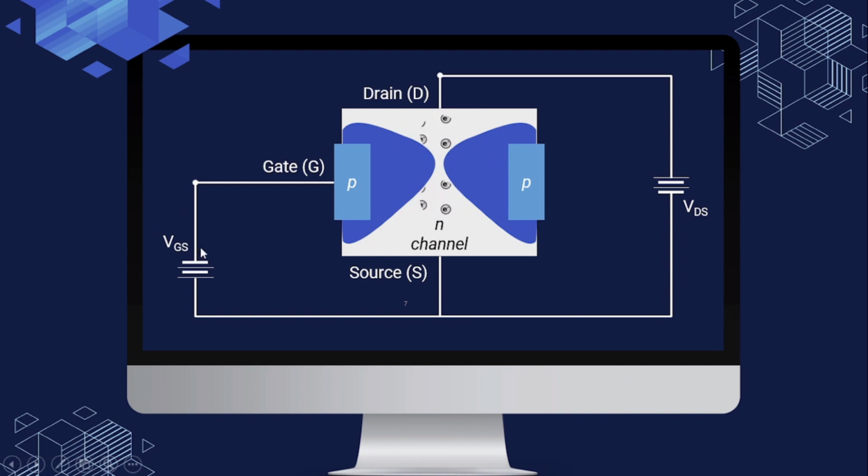When this reverse bias is increased further, the channel is pinched off, completely stopping current flow. The voltage at this point is called the pinch-off voltage. That's why the JFET is called a voltage controlled device. The voltage at the gate controls the width of the depletion layer. The gate current is ideally 0 because the gate-channel junction is reverse biased, giving a JFET a very high input impedance.